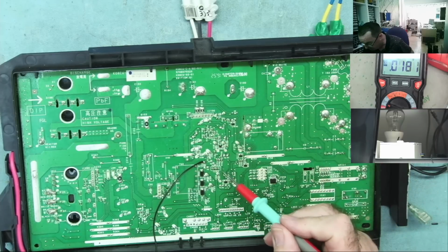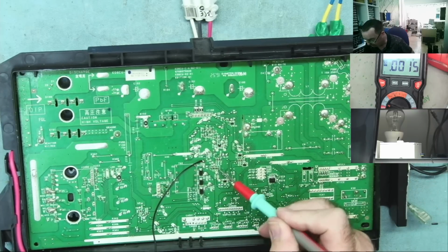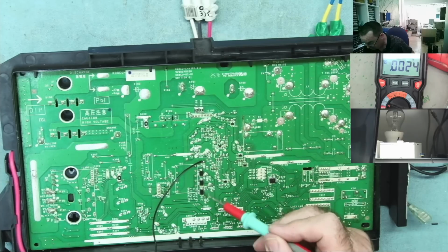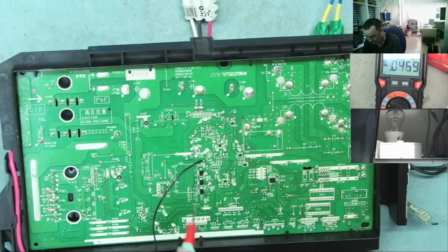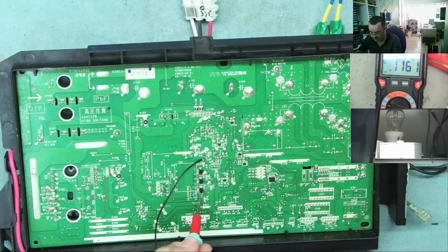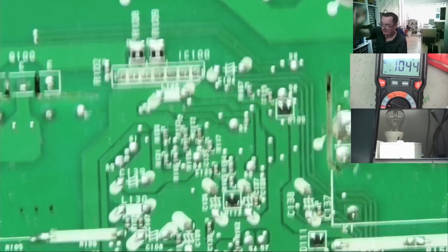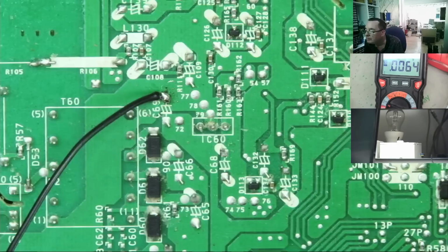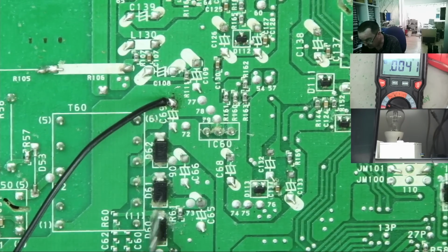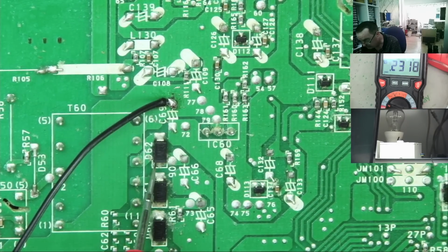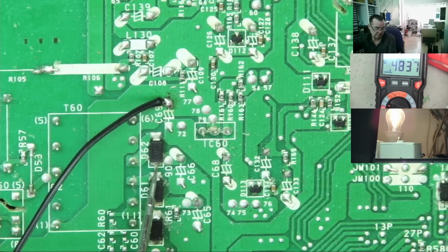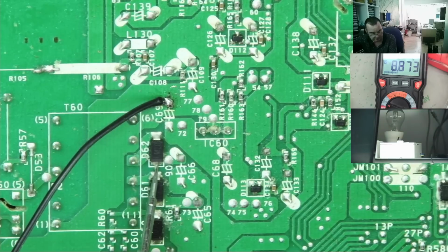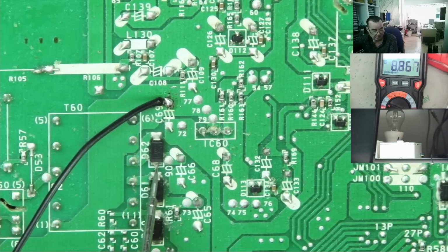Let's try that again with the bulb in and let's check the output of the voltage regulator and these diodes. In fact, let me just go to these diodes. Let's see if I get any voltage here. Okay, do I see anything? Make sure that is the DC end. I think it is. Yeah, the one with the stripe. Let's see. So on here, well, we do have some voltage. Not a lot. Oh, 8. We have 8 volts and it's dying away, yeah, because I switched it off.